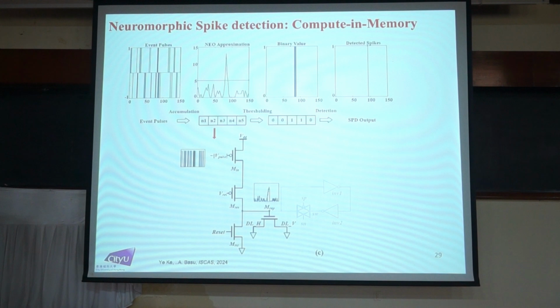So we have two sets of thresholding: one is thresholding this count, and secondly thresholding the number of ones in a certain time period. The first thresholding happens like this. You shut off the SRAM using the switch, and you just accumulate pulses on this capacitor. So it's an analog accumulation that's happening. That's what we are doing for this counting part.